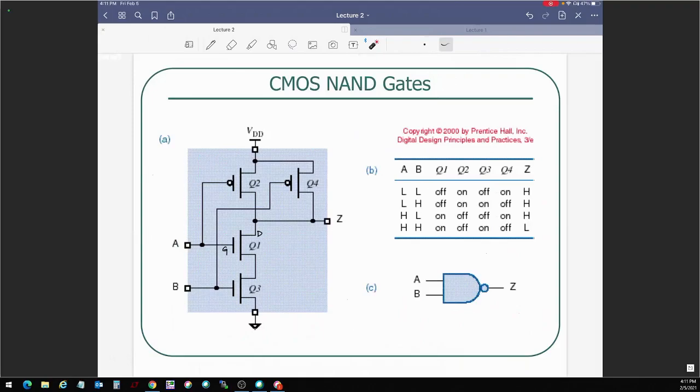All right, so here we have 10 more minutes, you guys. Let's get into NAND gates. This is the place where things get easier. So let's take a look here. For NAND gates, what we said earlier was we need switches in series for NAND as well as AND.